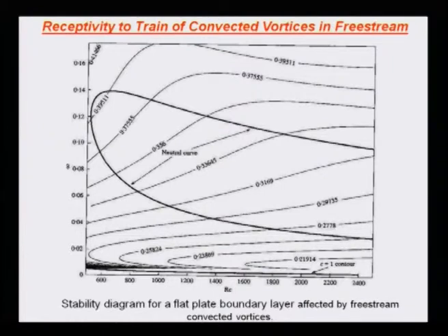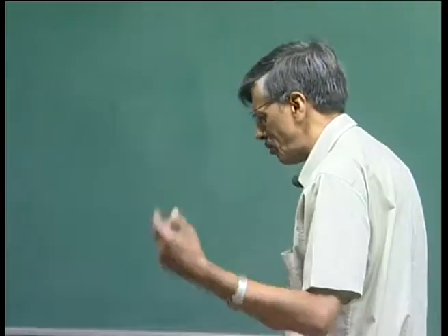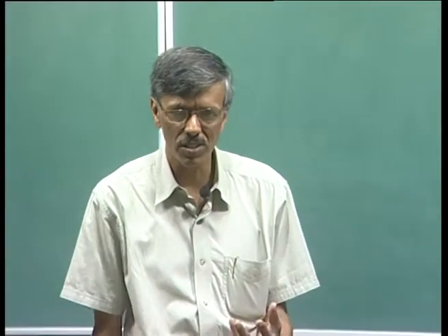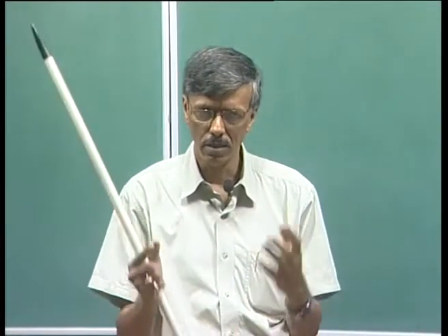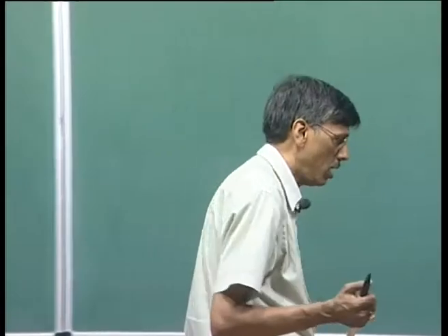So this particular route of creating instability by viscous vortices moving in the free stream is a very, very potent one. And since this creates wave packets and not a single wave, we went with the crowd and called it a bypass mode, but the constituents are still the Tollmien-Schlichting waves. So we are getting a wave packet constituting many, many TS waves. That is what we should be looking at, and what we do is go ahead with the calculation.